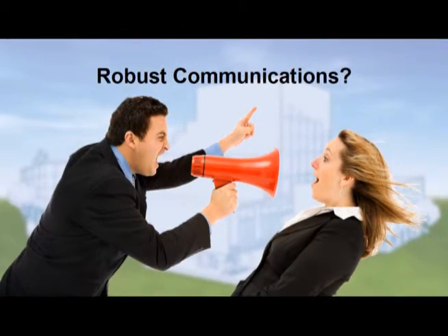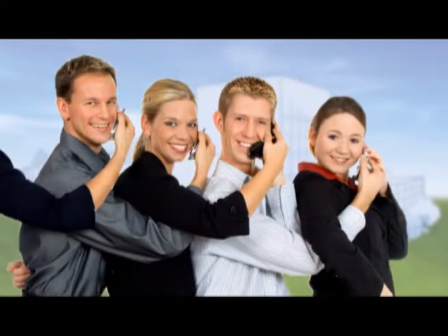Robust communications. We don't like it when people talk down to us, and we generally make friends with people we enjoy within our peer group. Something similar can be said about BACnet devices. Device communication generally works best among peers. Is the network architecture of a system you are considering true peer-to-peer? Peer-to-peer devices can effectively communicate with any other device in the system that BACnet allows. No middleman is required to pass data from one device to another.